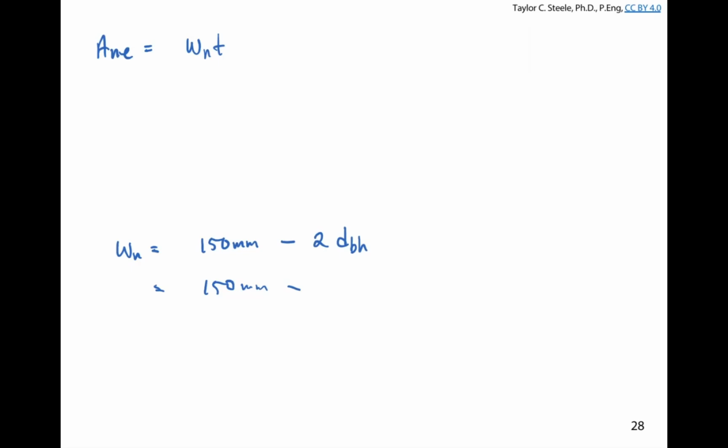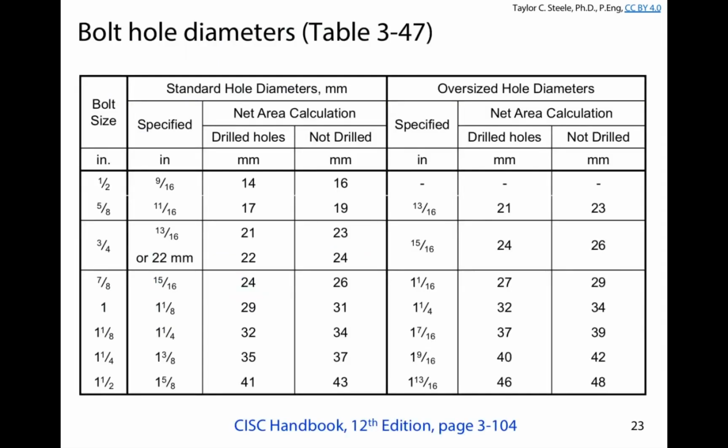Well, we can come to the table here. And one question was, do we assume drilled or not drilled? It's conservative to assume not drilled. At the same time, if you're the connection designer, you know what the people downstairs are doing. You're not going to be sitting in the office while you watch them build it and wonder, are they drilling it or are they punching it? You'll see them do it and you'll know what the people in your shop do. 9 times out of 10, they're going to be drilling those holes.